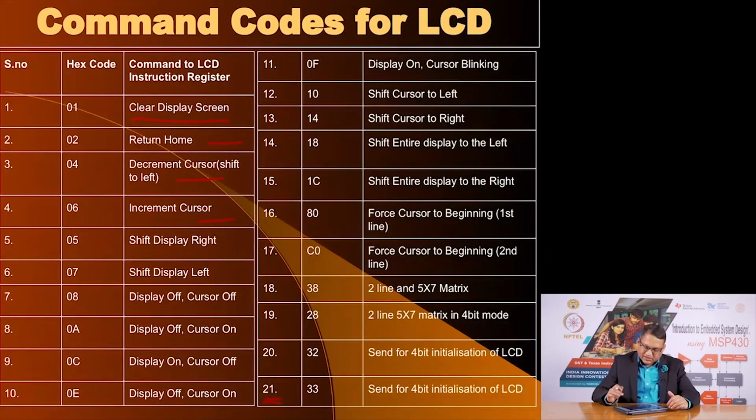In fact, these two commands allow you to tell the LCD that no, we do not have 8 pins to communicate to you and we are going to send information on 4 bits also. So, you have to send these commands, and we will see briefly how you send these commands. So, you have an 8-bit mode and a 4-bit mode.